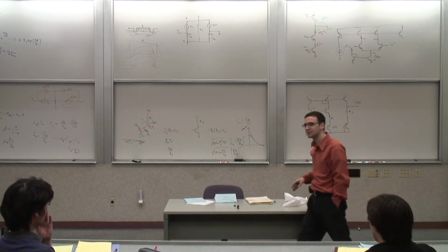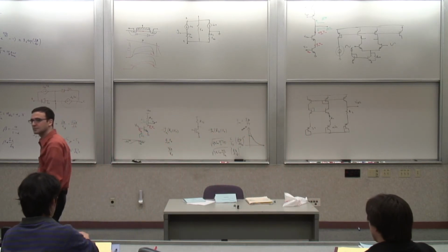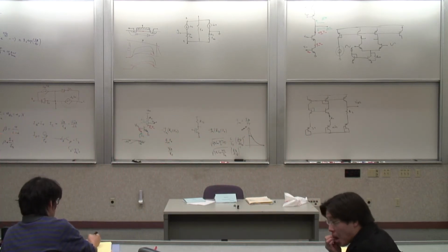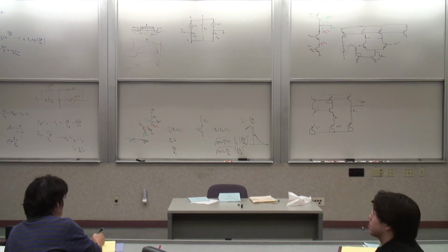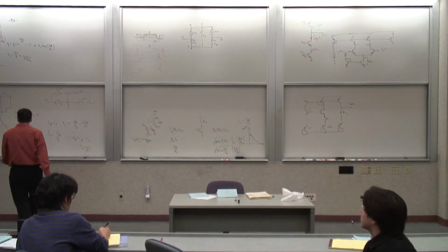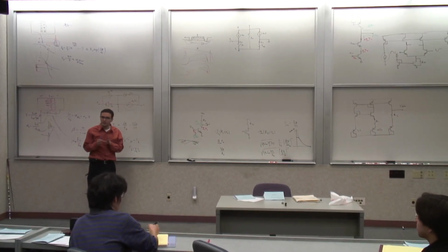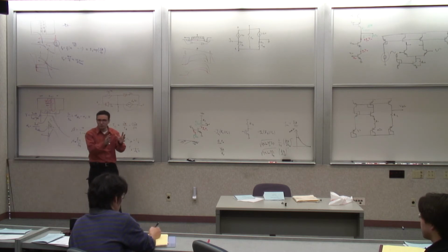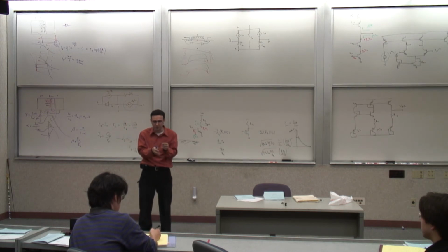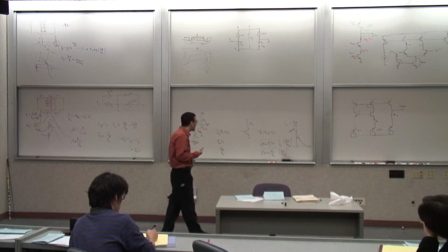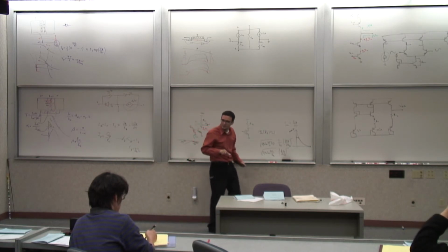Okay, yes. If you're given a circuit, how do you determine which transistor goes into saturation, how much is the maximum voltage? Okay, well, one way to deal with that, which works most of the time, is that you can start with the circuit from a large signal perspective, assuming that the transistor is in the forward active region. And then don't do the whole thing, just look at the stage in question, the transistor in question, and try to determine with that assumption what the DC levels are, the current, and come back and see if it's consistent. Let me give you an example.